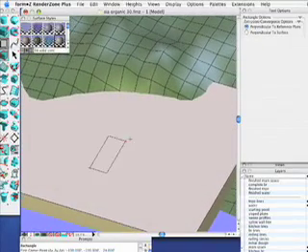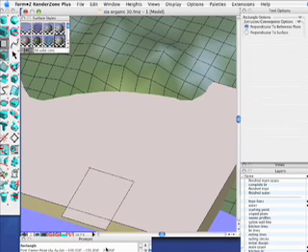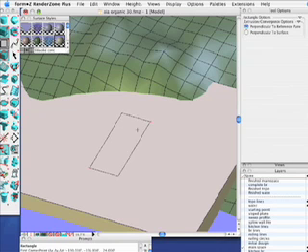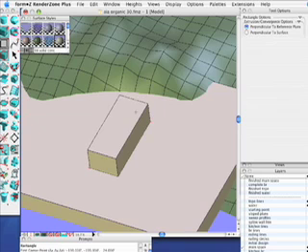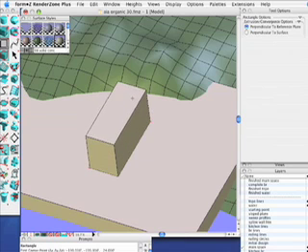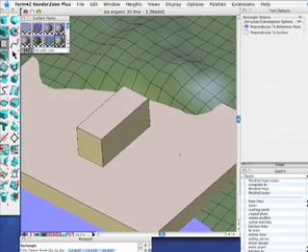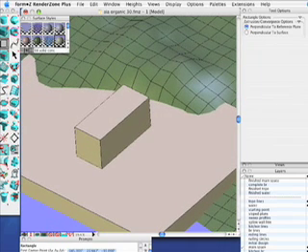And I'll start out with a rectangle. Notice down here in my prompts palette, you'll see a lot of dimensions flying around as I'm working. If you want, you can actually key in very specific dimensions if you need a very accurate dimension. So for example, I'll type in 30.1 feet, so you can work in feet with decimal. I'll type in, for the other dimension, 70 foot, say 4 inches, so you can work in feet and inches. You can work feet and inches with fractions. You can work in English units. You have a lot of choices and flexibilities when it comes to that.